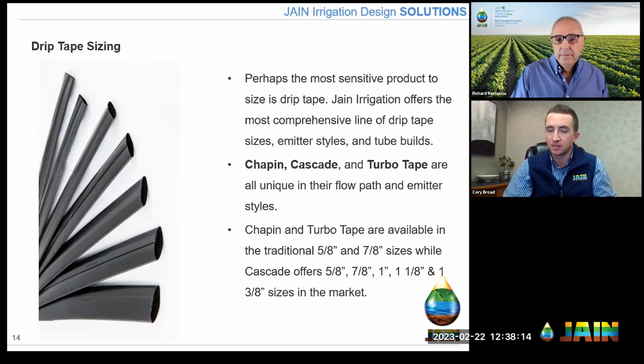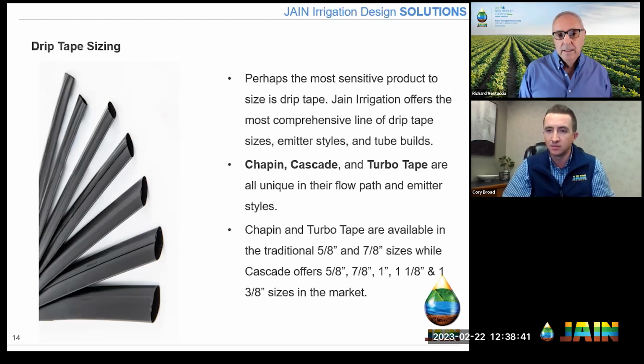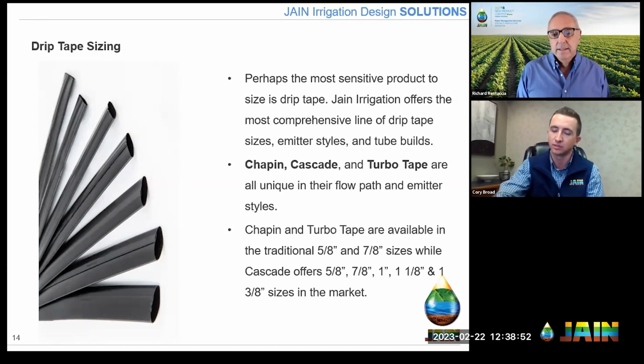Chapin and Turbo Tape have a continuous flow path, everything from ultra low flow up to really high flow products. They're available in the traditional 5/8 and 7/8 sizes, whereas Cascade still has 5/8 and 7/8, but also has 1 inch, 1.125, and 1 3/8, because it has a discrete emitter welded inside of it. Almost similar to Amnon and Top Drip earlier, it's what we would identify as a thin wall emitter line. But as we talked about earlier, because it's used in corn and cotton and tomatoes and all these things, it gets lumped in with drip tape because of the commodities or agricultural goods that it serves.